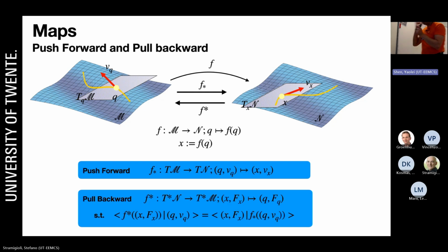And this is pretty deep if you think about it. So you can never see a differential map separated by its dual. It's the same thing. And that's what is going to be embodied in the modeling we'll start today. When there's a map between velocities, there is also a map between forces. You should not even separate them. If you take them all together, modeling becomes very, very powerful. And this is called the pullback.